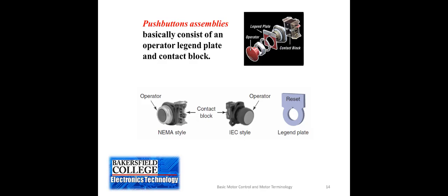So you're not necessarily having to buy just one normally closed push button switch, and that's the only connection that you have. But you can add these contact blocks, just stack them one on top of the other or put them one on either side, and those will make the switch into the configuration that you want.